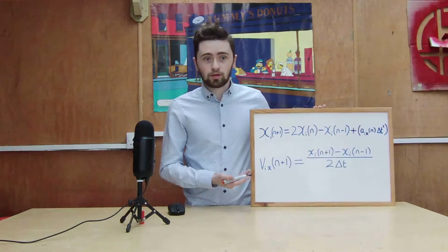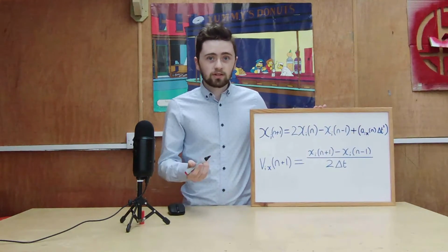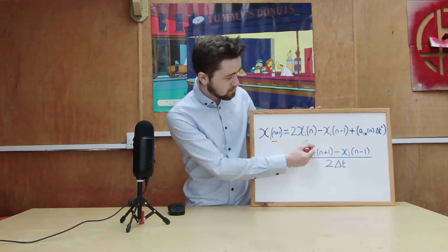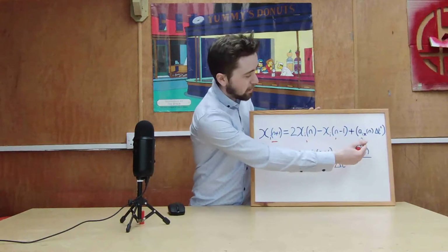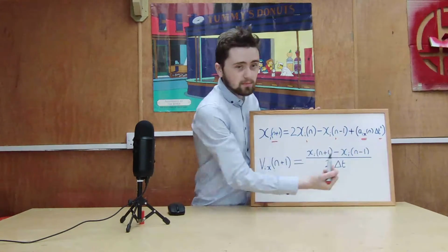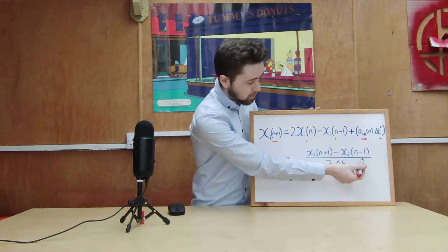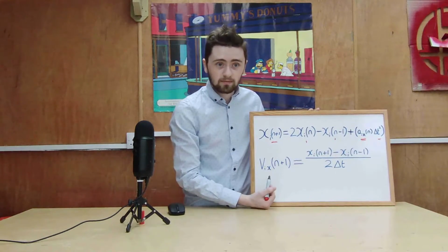As it's a computer simulation, we need to solve this for a finite number of discrete time intervals. And to do this, we're going to use the Verlet equations shown here. What these equations tell us is that we know where an atom is going, depending on where it is, where it's been, and how much it's accelerating for a given time step squared. And once we know where it's going and where it's been, we can calculate a velocity.